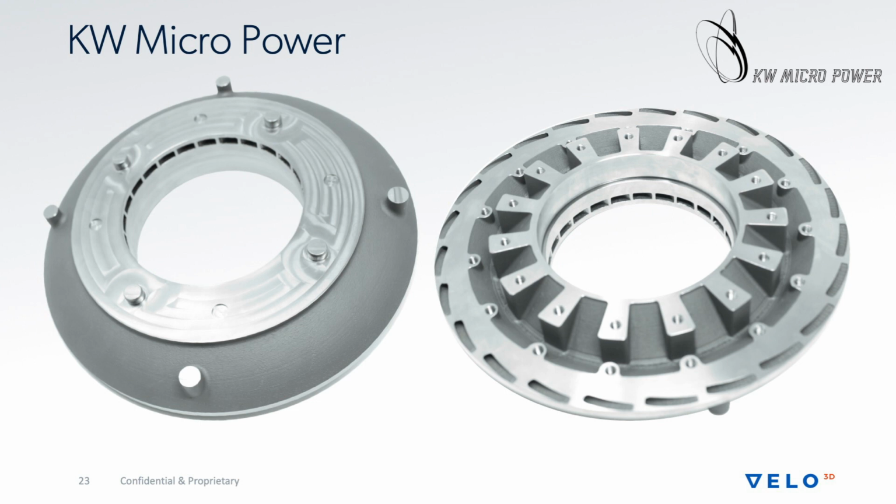And so when you approach looking at these really low angles, you can think about this kind of like a constrained plane. You've got a rectangular profile, and so you've got a planar surface that's changing and sweeping through angle, but it behaves like a plane at any point in time. It behaves like a constrained plane because you have these vanes separating the ports. And so we can go back and think about the constrained plane rule, and that if you get down into these areas that are down to 10 degrees or so, they're safe because of how this part is constrained.